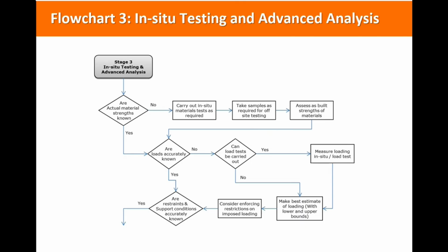Now, very simple load tests in buildings usually involve water bags. You get a bag, fill it with water and see how the building performs, which is usually the deflection of the floor or the deflection of the beams supporting the floor. So it's measured loading using an in-situ test, and that gives you a best estimate of how the floor or the beams perform under their load. If they perform poorly, you may end up putting restrictions on the load.